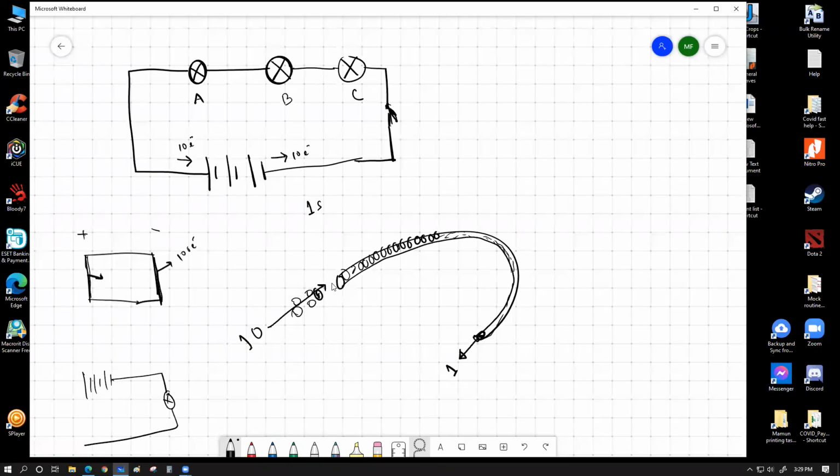This is why whenever the switch is closed, none of the bulbs glows first. Each of the three bulbs will glow simultaneously. And if you switch it off, all three will go out simultaneously as well. None of them will glow up first, none of them will glow up last. Now, what happens to their brightness is a different issue. The brightness, I'm going to talk about with the electrical power topic after a while, and the brightness will be a part of that discussion. I'm just trying to tell you which one will glow up first and which one will glow up later. The answer is none. If the circuit is closed, all three of them will glow up at the same time. If the circuit is open, all of them will go out at the same time.